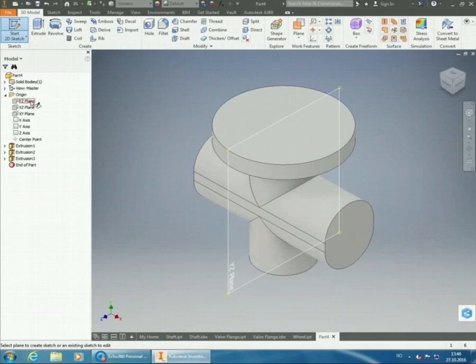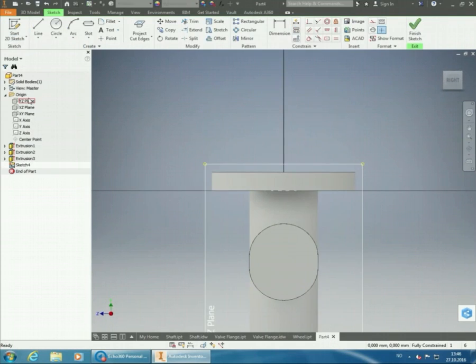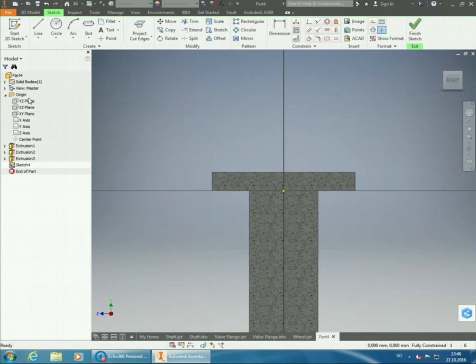So we'll start a new sketch, and either on this plane that's going through it that way, or on that plane. It doesn't really matter which one you choose. Just use one of those. Again, we'll click on the F7 so that we cut through our entire part. And we're going to use project cut edges to get these yellow edges on it.